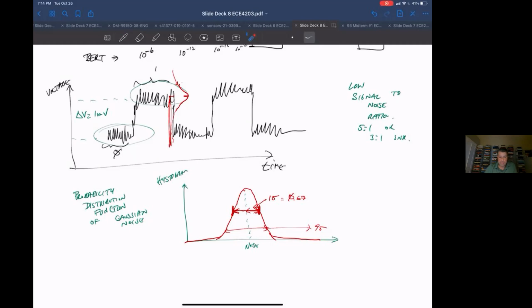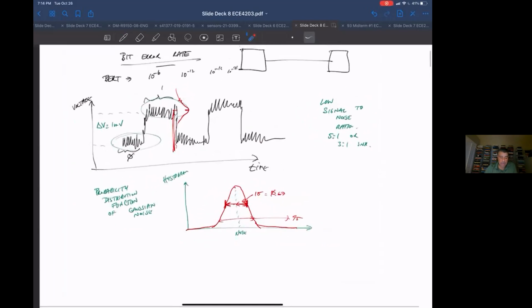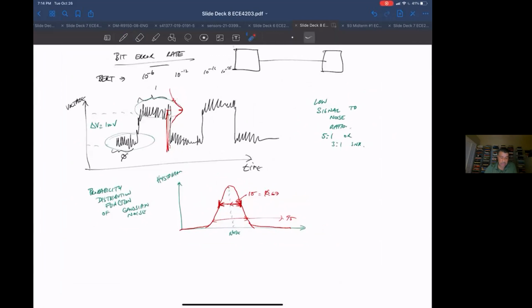And so you basically have enough error coding in your overall end-to-end system that says, okay, if every billion bits that I transmit, I get one error, I can correct it. Okay, now every billion bits sounds like a lot, but remember, if you're downloading a video signal, it's like a gigabyte. So if you had like a 1 × 10⁻¹² bit error rate, you could potentially get a lot of errors in that video.